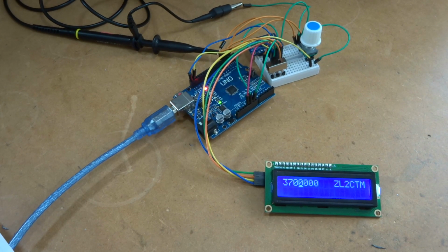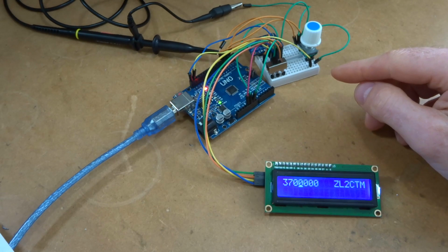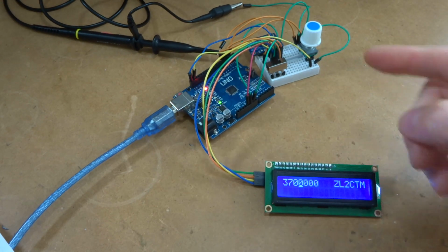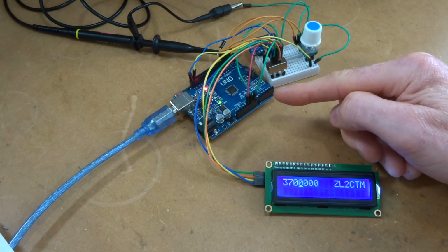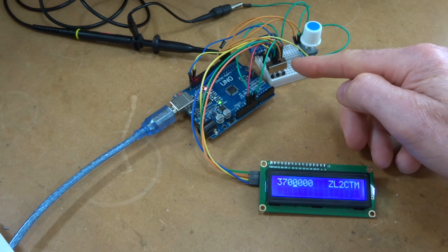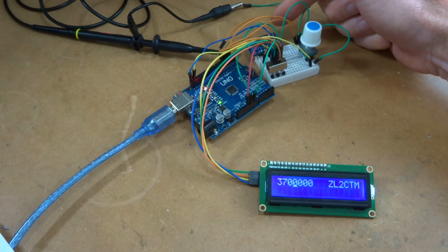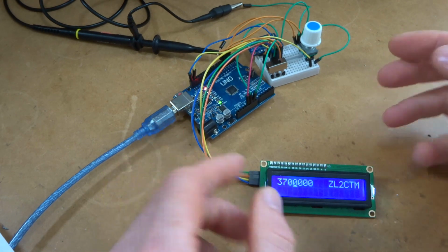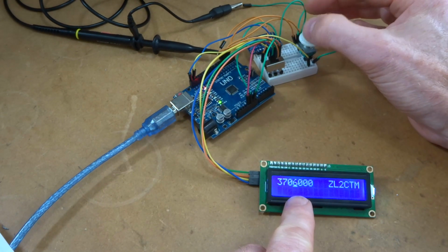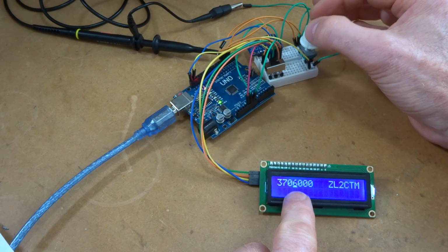Right, so what I'd like to do today is do the second part of that two-part video looking at the VFO. What I want to have a look at is the software side of the house required to drive the display, read the rotary encoder, read the band switch, and then send the necessary commands through to the SI5351. So before looking at the schematic, what we have here is the display down here, and the rotary encoder, which changes the frequency.